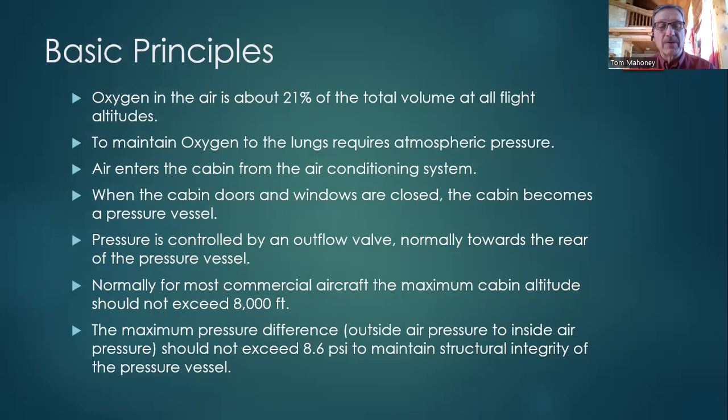Normally, for most commercial aircraft, the maximum cabin altitude should not exceed 8,000 feet, and the maximum pressure difference between the cabin and the external surrounding air should not exceed 8.6 psi, so that we can maintain structural integrity of the aircraft.